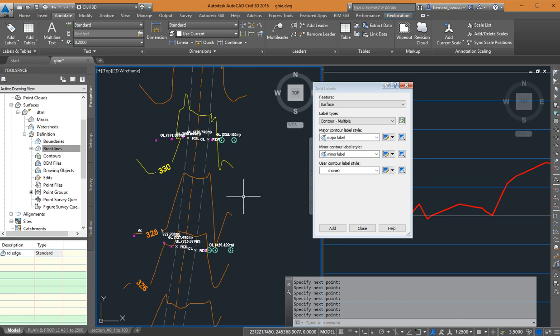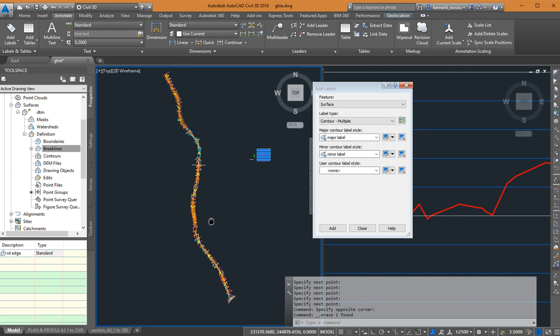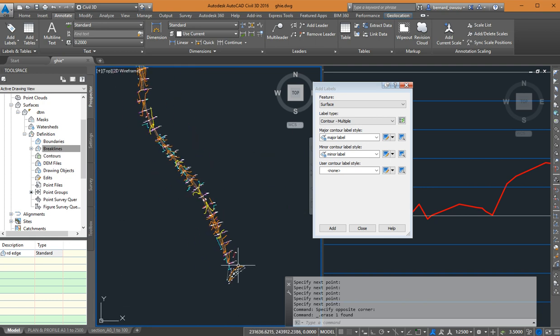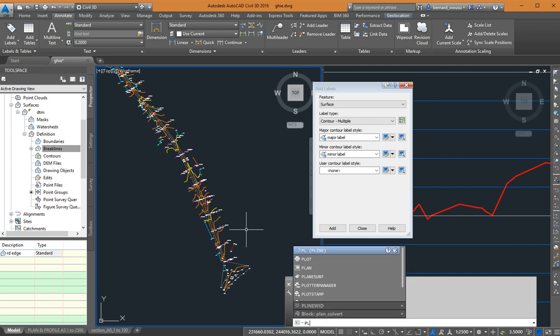So normally what I do is that I will not label it at this stage. I'll wait, do my center line. When I do my center line, I will create a copy of the center line to one side. I'll offset the center line, create a copy of it to one side, and use that to do the annotation from beginning to the end. So let's try that one and see. Let's assume that what I want you to do for me is just type PL for polyline. PL, polyline. Just type PL, enter.